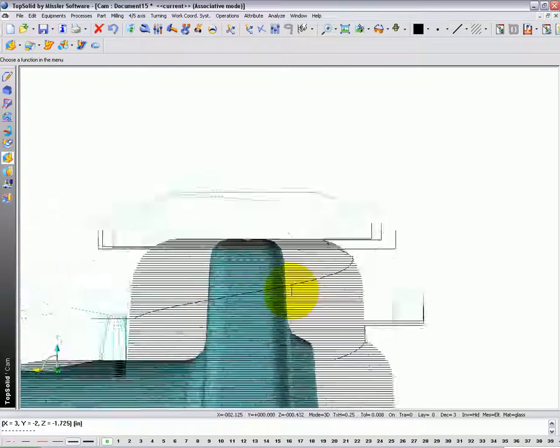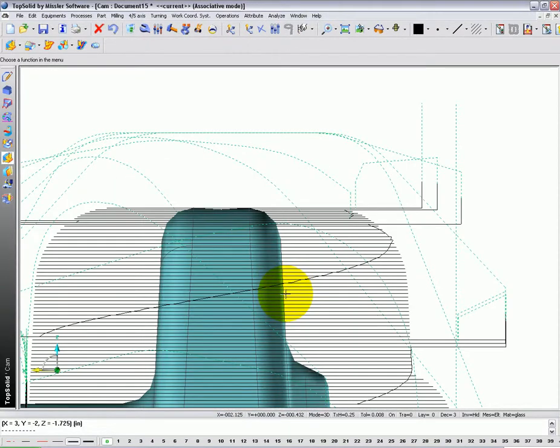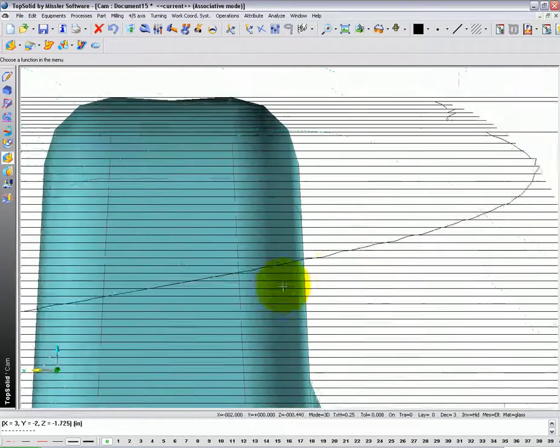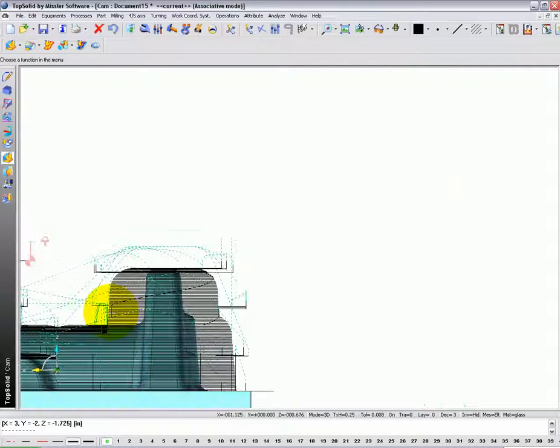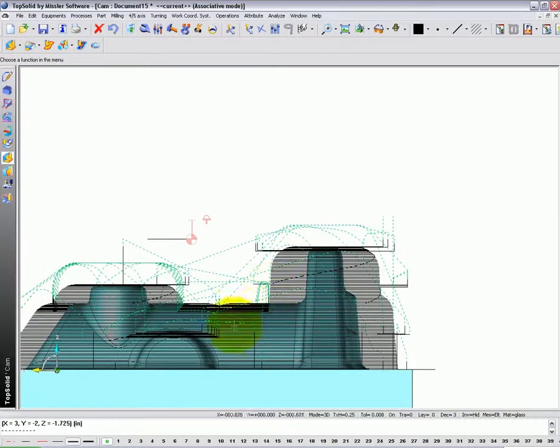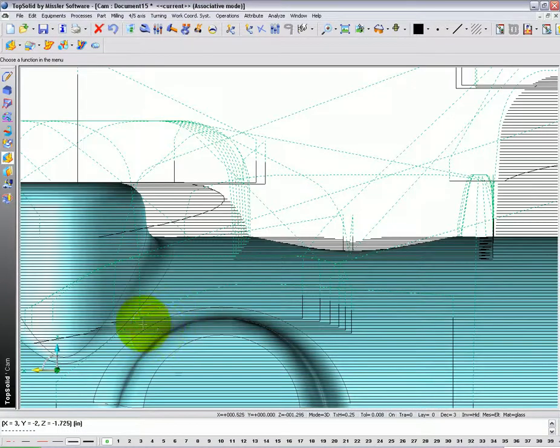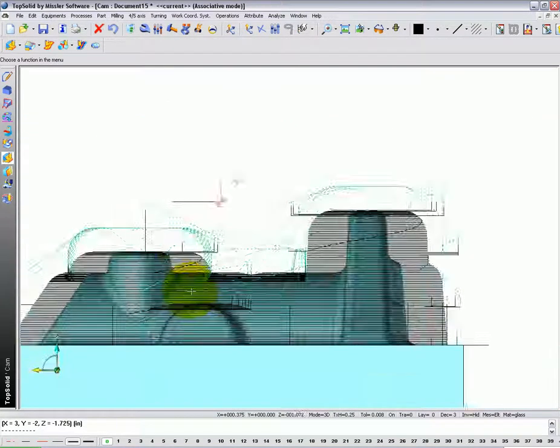Next, remember when I told you to set your lead in and lead out for other passes to ramp? Here you can see that the toolpath is transitioning at 10 degrees down very smoothly between each operation. Also, when we told it to optimize for scallop, you'll notice that it inserted some more toolpath, but only in the areas where we needed to, instead of going all the way around the part and wasting movement.